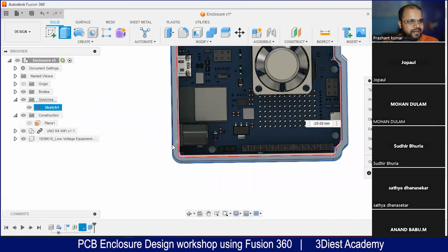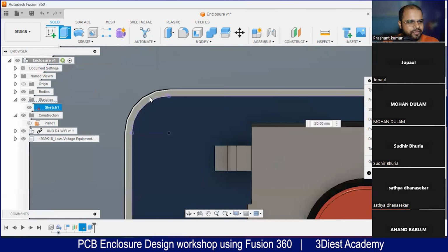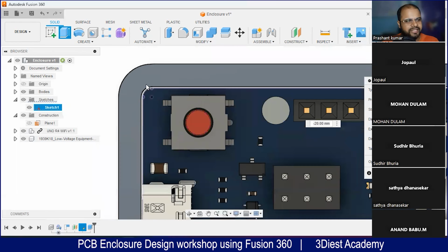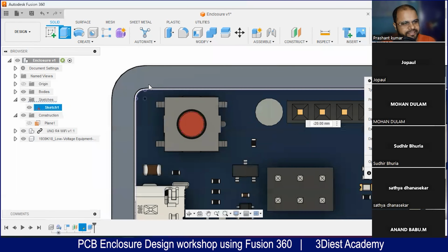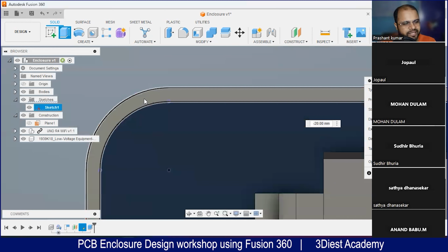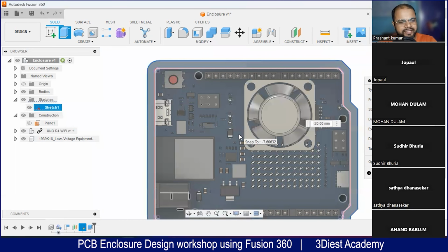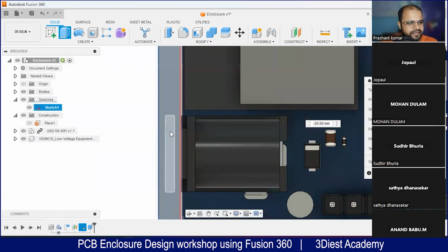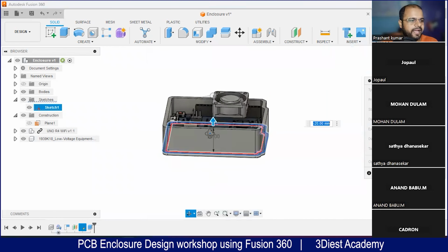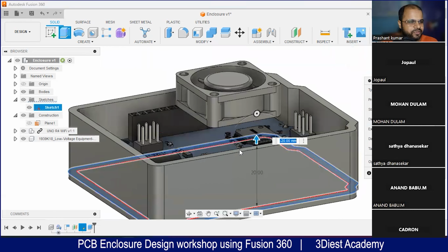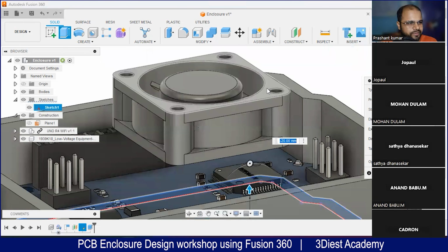Here you can see. Now if you go on to the top view, you can see we got space over here, right? We got clearance. So that's why I had created this 0.2 millimeter of offset over here, just to make some clearance with the walls of my PCB board. So the things will completely fit inside this complete setup. Here you can see.